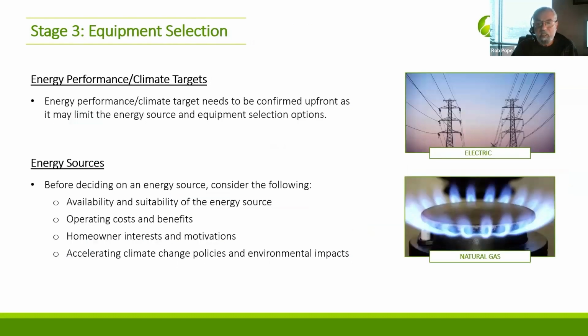Equipment selection. So once you've got the load calculations, you got to select the equipment, and it's pretty important. There are third-party agencies that evaluate equipment, test it, and so on, and verify capacity and efficiency. You got to check those. You don't want to depend on the manufacturer's literature alone. That's important to get as well, right? But you got to select equipment based on the required capacity to keep the home comfortable.